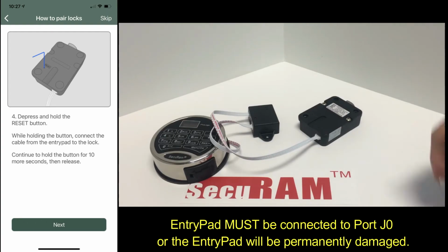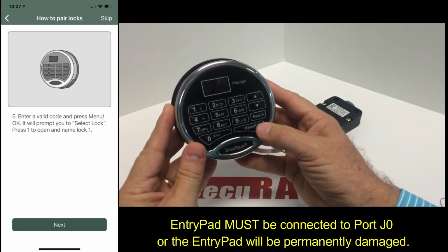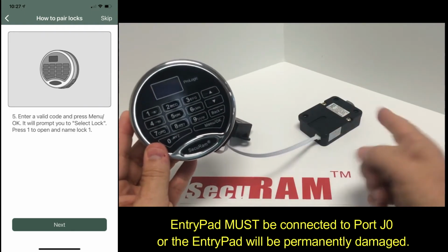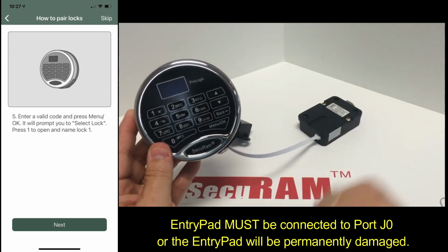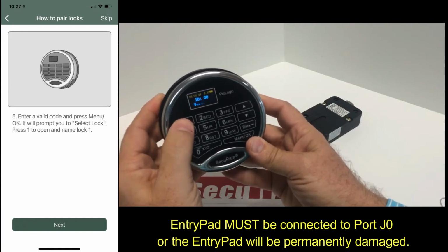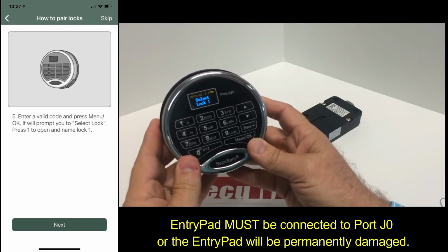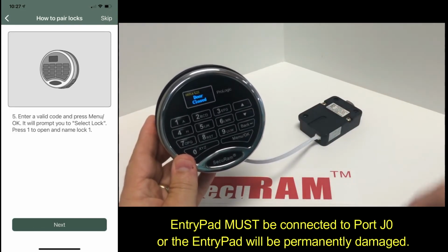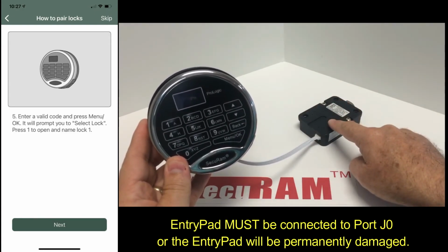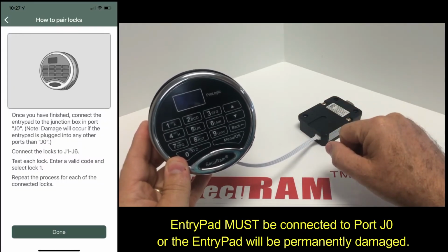I can now release. Now, in order to name this lock, I would enter my code and it will ask me which lock I want to open. I'll select lock number 1 because I've only got one lock connected, and it will name this lock as lock number 1. So I enter the supercode, and you'll see it says verified, then it says select lock. I say 1, and it'll send a signal to this lock, so this lock opens. This lock is now named in the memory of this system as lock number 1. We can now go ahead and name the second lock that we're going to connect to this.